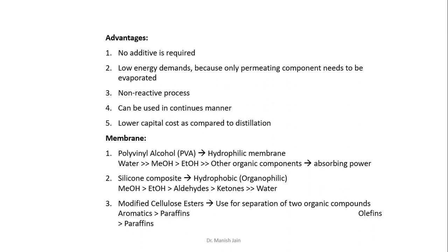Now the fifth advantage is lower capital cost as compared to distillation. We know that distillation setups are huge and require a lot of capital cost, but generally membrane based pressure setups are very small in size and require a relatively low capital cost.